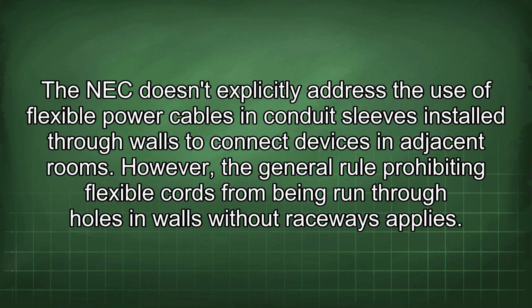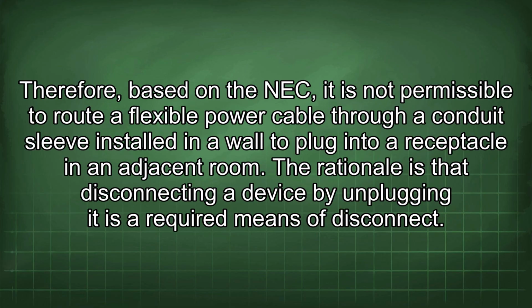The NEC doesn't explicitly address the use of flexible power cables and conduit sleeves installed through walls to connect devices in adjacent rooms. However, the general rule prohibiting flexible cords from being run through holes in walls without raceways applies. Therefore, based on the NEC, it is not permissible to route a flexible power cable through a conduit sleeve installed in a wall to plug into a receptacle in an adjacent room.